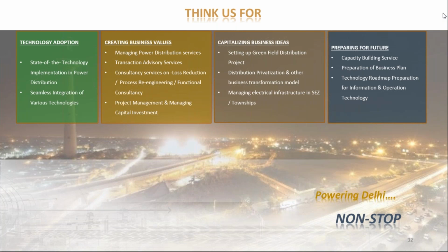Because if you are putting very big conductors like 30 kilometer cables, or let's say OHL ABC conductor, or whatever conductor you are utilizing, and you are putting a load center very far, in that case you have more energy losses. So selection is not only on the current rating, but also the voltage ratings, the sheathings and the losses of the conductor itself. So selection of the conductor is not based on one criterion only, the ampere ratings.